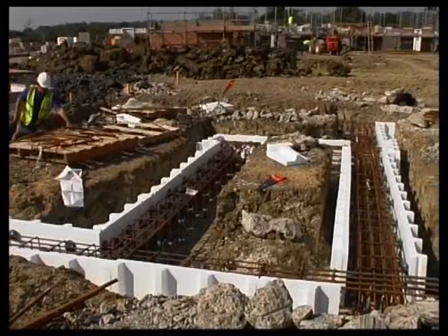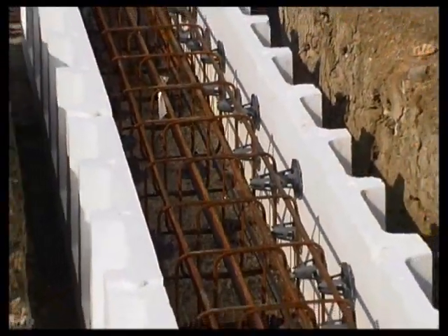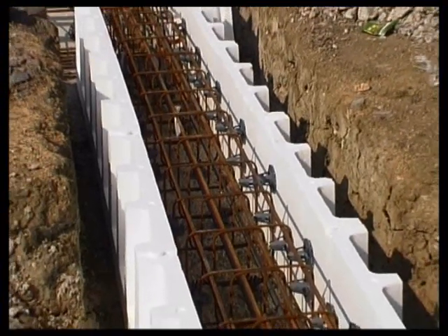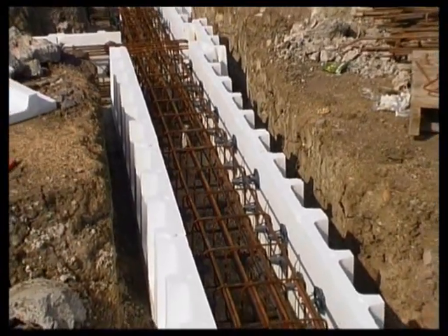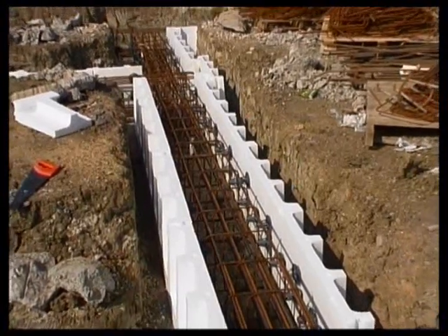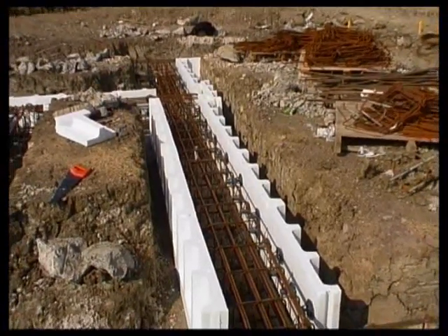This permanent polystyrene formwork acts as a compressible layer and is sometimes used in clay soils to prevent possible expansion of the clay cracking the beam. It may be required underneath or either side of the concrete.